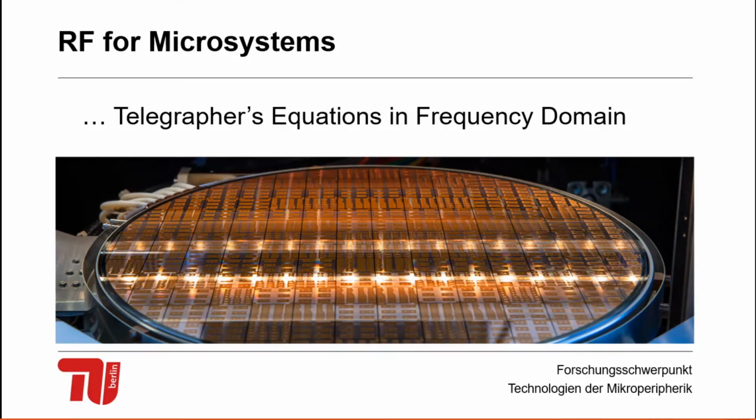And what we assume now is that we have a sine or cosine wave. So the dependence of voltage and current on time and space takes the form of a harmonic wave, a time harmonic function. Now when we do that, we can describe the whole function in terms of a frequency, so one frequency if we just have one main function. And this then holds true for every point in the transmission line. And by using complex terms, we can solve the wave equations in the frequency domain. And by implementing Fourier transformations, we can provide solutions for almost arbitrary time sequences.